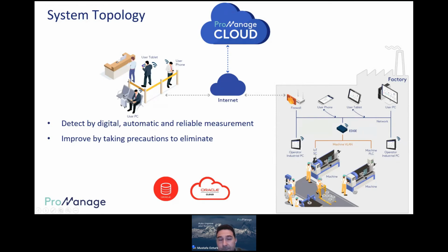And we support Mitsubishi or Siemens PLCs, or if you have OPC UA connectivity to your machines, or if you have CNC machines with MTConnect or Focus protocol, or if you have plastic injection machines with Euromap, we support Euromap protocol, or MQTT protocol. We have a lot of protocols that we support natively, which means if you have a smart machine, it's more likely that all we have to do is connect that machine into the same local area network, and the edge software will start collecting data.